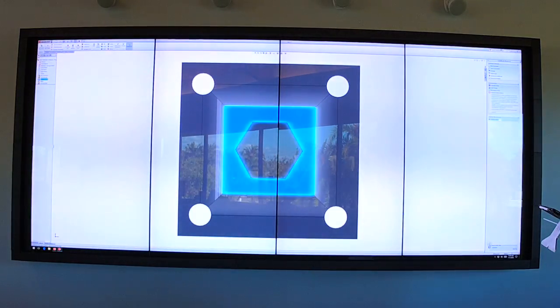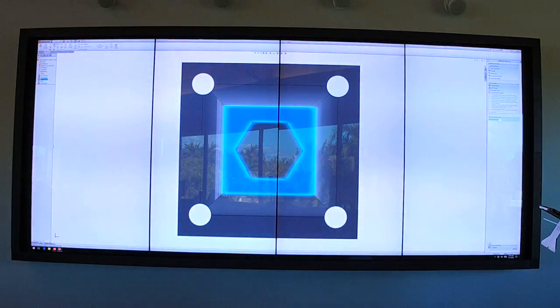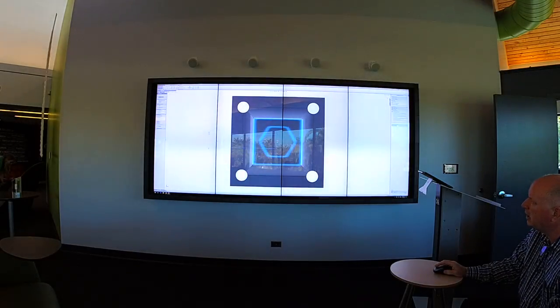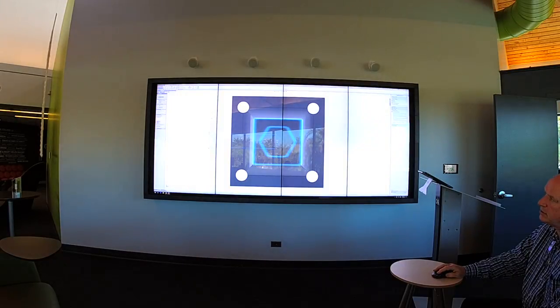So again, we're going to go back into the sketch and create a hole right in the center. I'm just going to guess this at the moment. We can actually tell it what size the hole is if we want it to. We can create our smart geometry if we want to make it a specific size. So if I go to smart dimensions again and double click my hole, I can make that right now. It is 6, so let's make it 6 millimeters. So that's my bolt size.